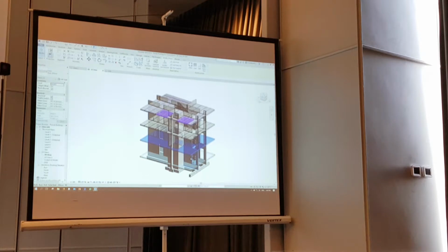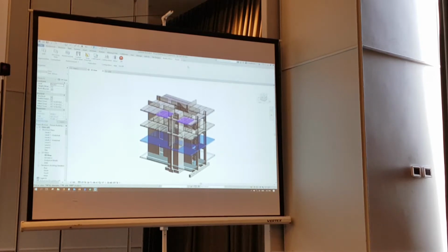So to do that is very easy. All you need to do is just go to the precast and click on the split button. Okay? So remember that we did a segmentation setting just now. Maximum height, maximum length, minimum height, minimum length, maximum weight. So based on that setting here, it will split your models into each of the panels. Okay? So you click on the split.